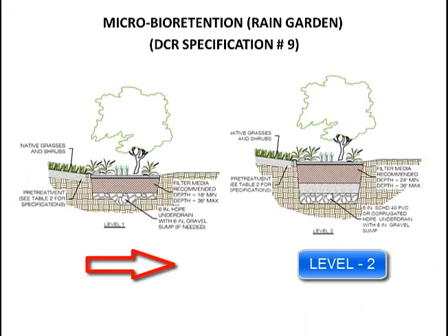Bioretention creates a good environment for runoff reduction, filtration, biological uptake, and microbial activity, and provides high pollutant removal. Bioretention can become an attractive landscaping feature with high amenity value and community acceptance. Small-scale or micro-bioretention used on an individual residential lot is commonly referred to as a rain garden. The major design goal for bioretention is to maximize runoff volume reduction and nutrient removal.